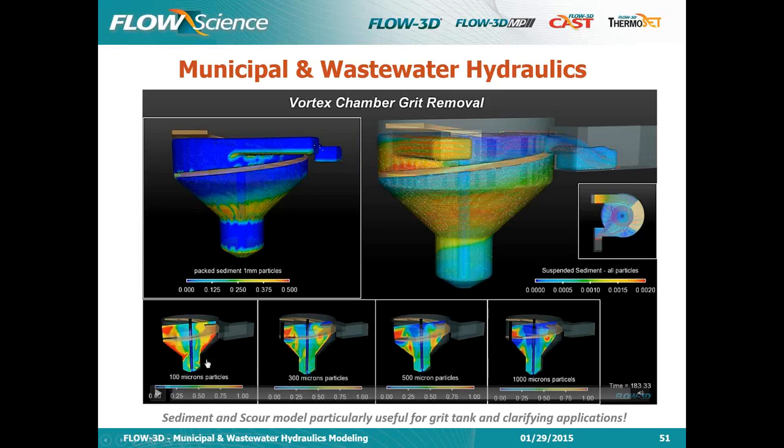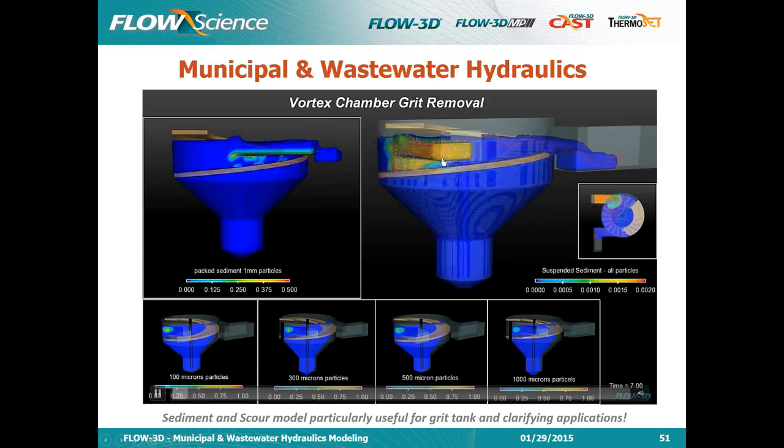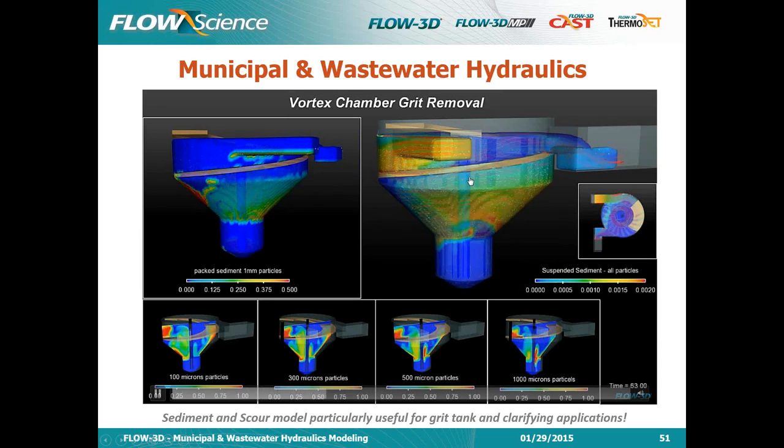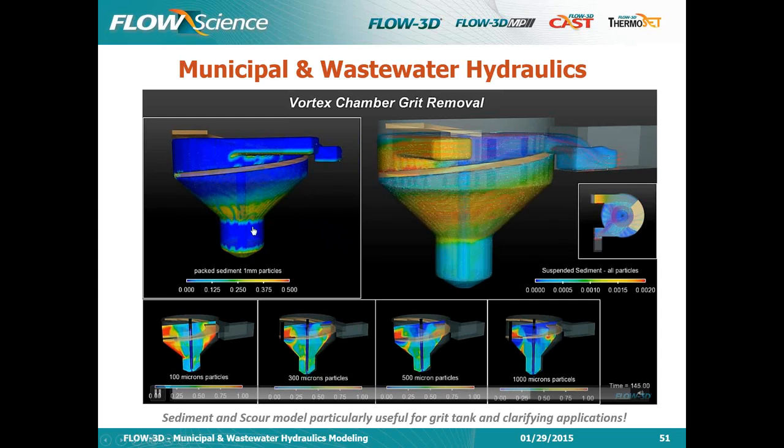And what we see here, these are 2D slices. I'll maybe just play this once again. What you see is the water coming in, swirling around. You can see the streamlines a little bit, and then going up here. So this is a view of the suspended particles, all of them, and this is a view of the packed sediment. So we see that the sediment, by and large, is packing on this section of the structure and at the bottom, of course. And then in the suspended case, we don't have too much suspension here. It's all happening here. Now we can refine this by particle size.